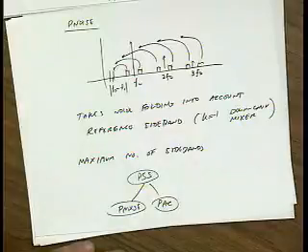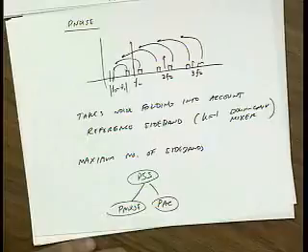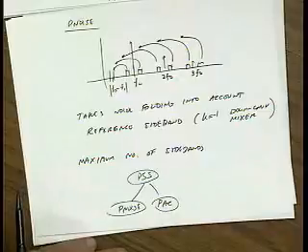Yes? Do you also need to specify the bandwidth over which noise is integrated? Because bands all have B's in the equation. Yeah, it's a good question. You can tell it if you want integrated noise or spot noise. And you also have to tell it where your input and output port are. So it's a lot like just doing regular noise analysis in that way.